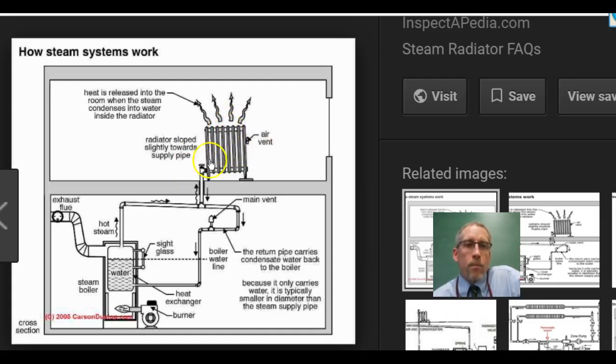And then because the heat was always here by the heat registers or the radiators, the question is, how do you get the rest of the room or the rest of the house to be warm? And this relies on convection. So remember that warm air tends to be less dense, and less dense things tend to rise.